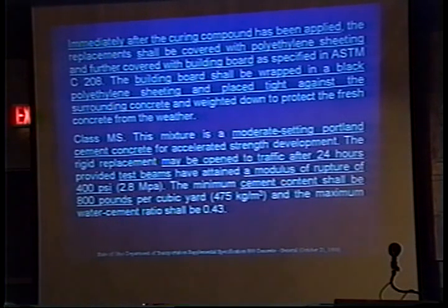That doesn't mean 4 hours from now. It doesn't mean tomorrow. And don't rely on sealers to do that job for you. I hear a lot of people run around saying, well, I'm going to seal my concrete. They don't get it. If you seal it a week later, the damage is already done. Don't expect the sealers to make the concrete come back to life, because it won't happen. So you've got to get it covered up immediately.